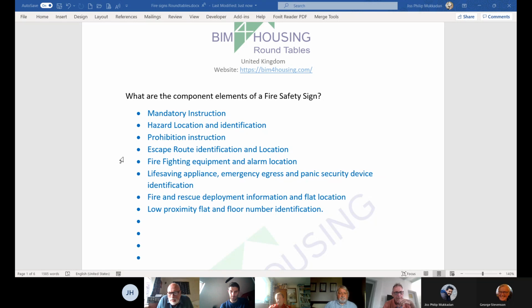I think there is a difference between what we recognise as the fire exit signs and other signs that may require illumination, Jim. Something like, say, an acid bath. Depending on the situation, that acid bath may or may not need to be illuminated in an emergency, and there should be a risk assessment to decide whether it is.